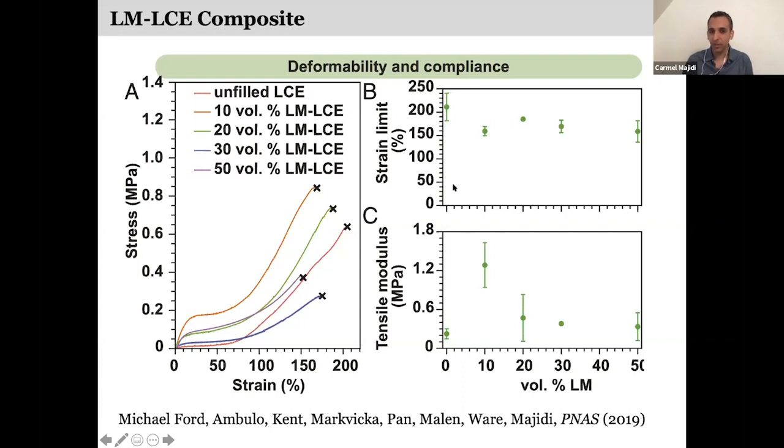And what that tells us is that we can take this material and stretch it to, say, 100% strain. It's not quite a linear response here, but we do see this monotonic response. At about 100% strain up to 150, 200, we're seeing roughly 0.2 to 0.4 megapascals of stress. That's pretty significant stress that these materials can support, fairly similar to the amount of stress that your natural muscle can support. With muscle, maybe you can go a few factors higher, up to about a megapascal, but still we're talking within the same order of magnitude.